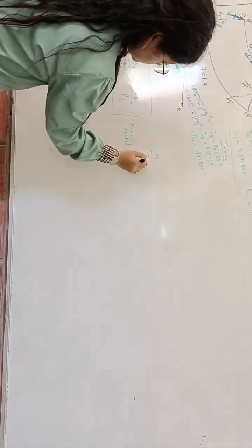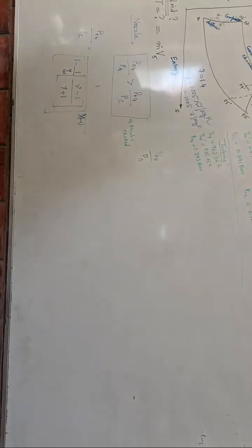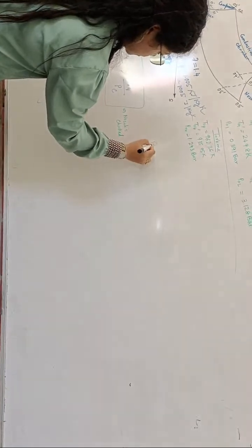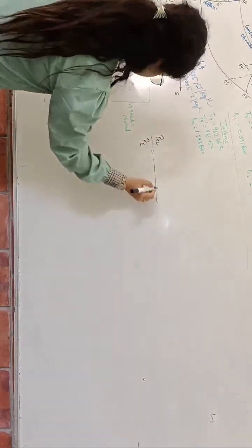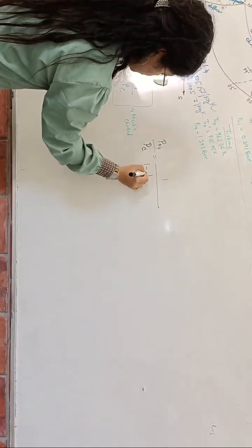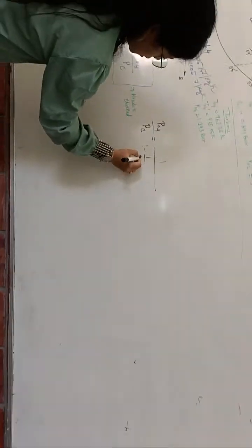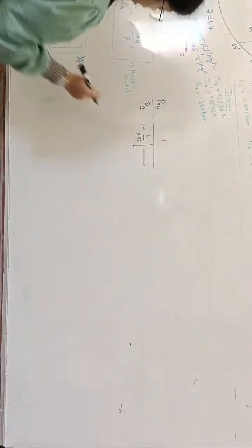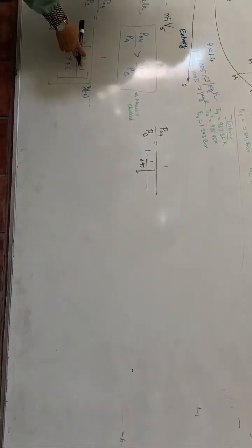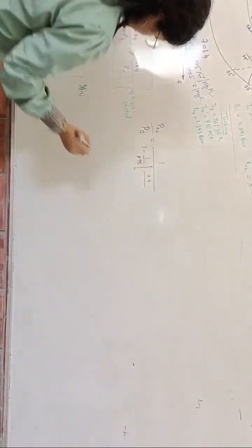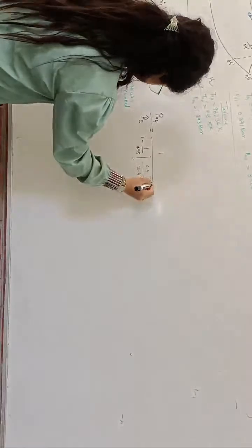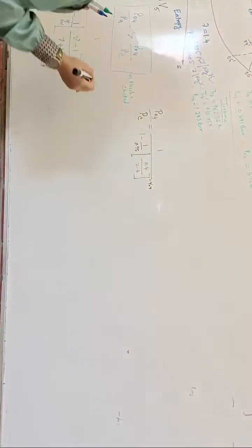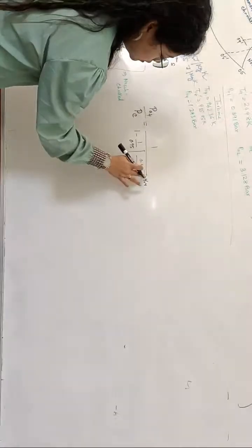P04 by Pc equals 1 by 1 minus 1 by, what's the efficiency value? 0.95. I'm just quickly writing: 1.4 minus 1 is 0.4, and plus is 2.4. Then we have gamma by gamma minus 1. That means power of 1.4 by 0.4. That is 3.5. I can say that.